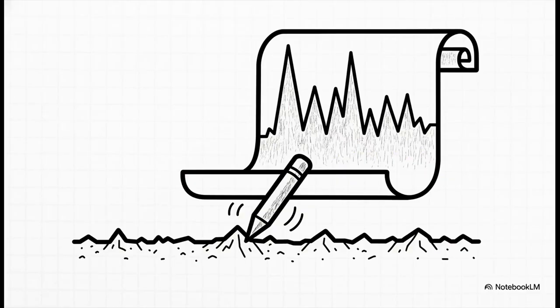To accurately map all these features, we use instruments called profilometers. Imagine a microscopic record player needle. A profilometer drags a tiny diamond stylus, sometimes just 10 micrometers in diameter, right across the material. As it moves, it records the minute heights and depths of these irregularities. Then, the machines deliberately exaggerate the vertical scale on the resulting graphs. They basically transform microscopic bumps into towering, jagged mountain ranges so engineers can actually study them.